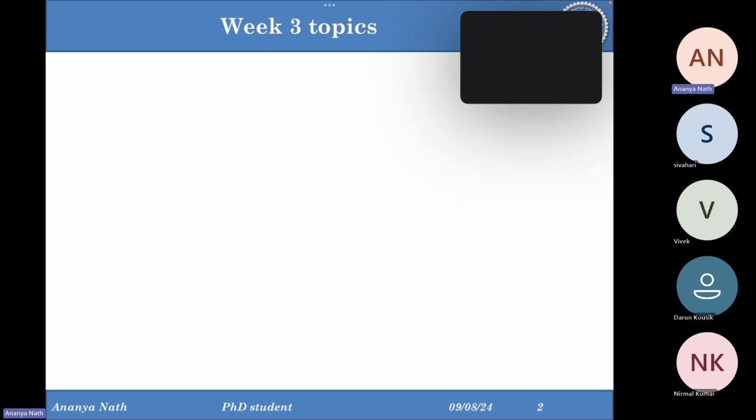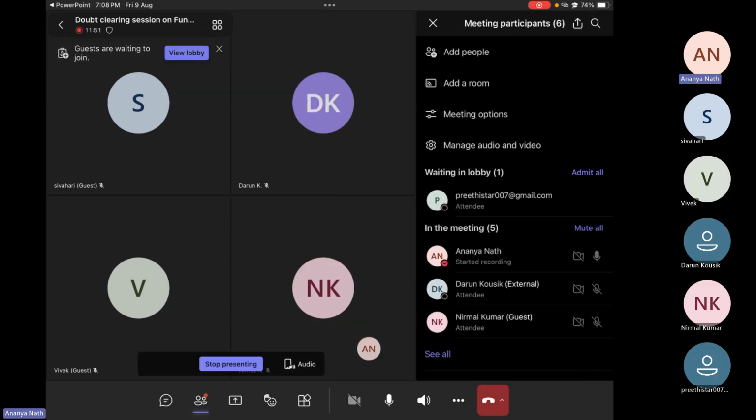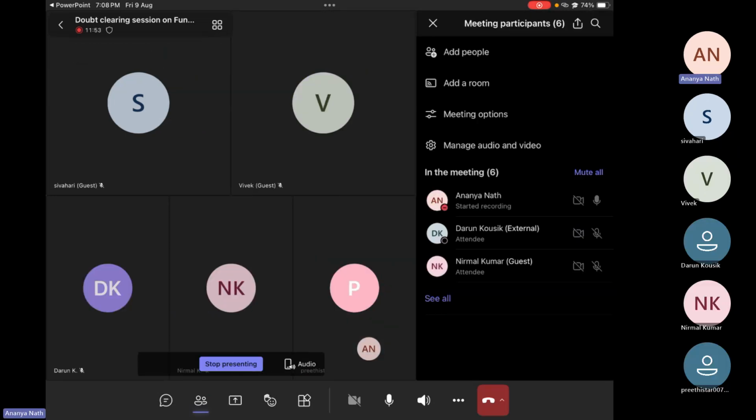And then from week 2, we got to know about direct slicing, indirect slicing, and uniform slicing. Slicing can be adaptive, with finer layer thickness in the parts where there is intrinsic structure, or where we need more accuracy, or where there is a curve or something different from a normal, very general structure. Then we had adaptive slicing, and then conformal slicing.